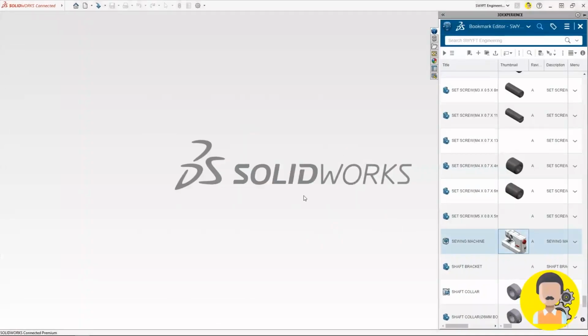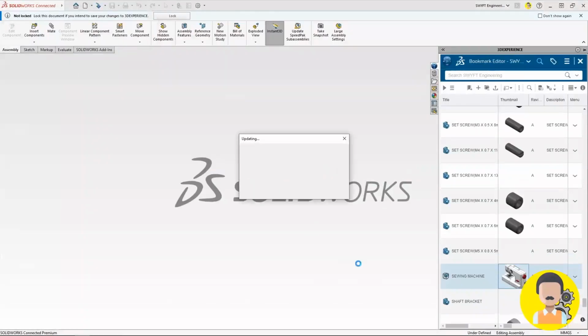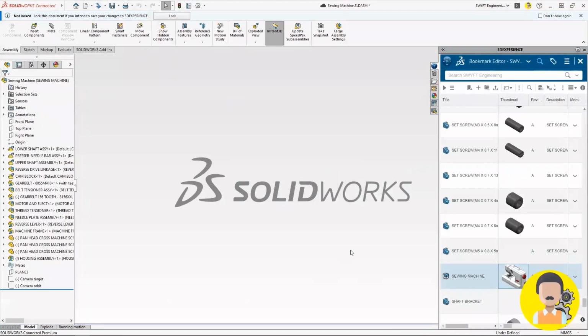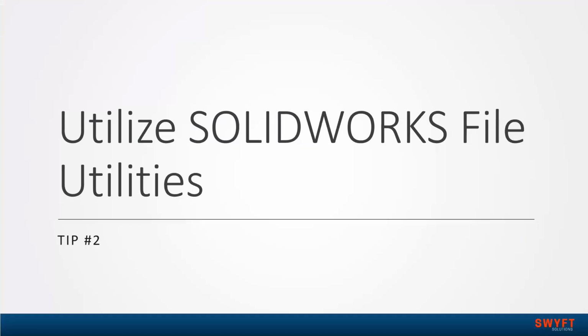And now when Lucas opens this up, it doesn't look for that local file location. Well, it does. It looks for a local copy on Lucas's computer. Any file that it doesn't find, though, it'll pull from the database rather than ask you to fix it. Otherwise, if it can't find anything, which in data management, it will always find something as long as it still exists, unless you deleted it. But if it can't find anything in the file system, it's going to ask you to go and find it for SolidWorks. It's going to bring up the dialog, browse for files.